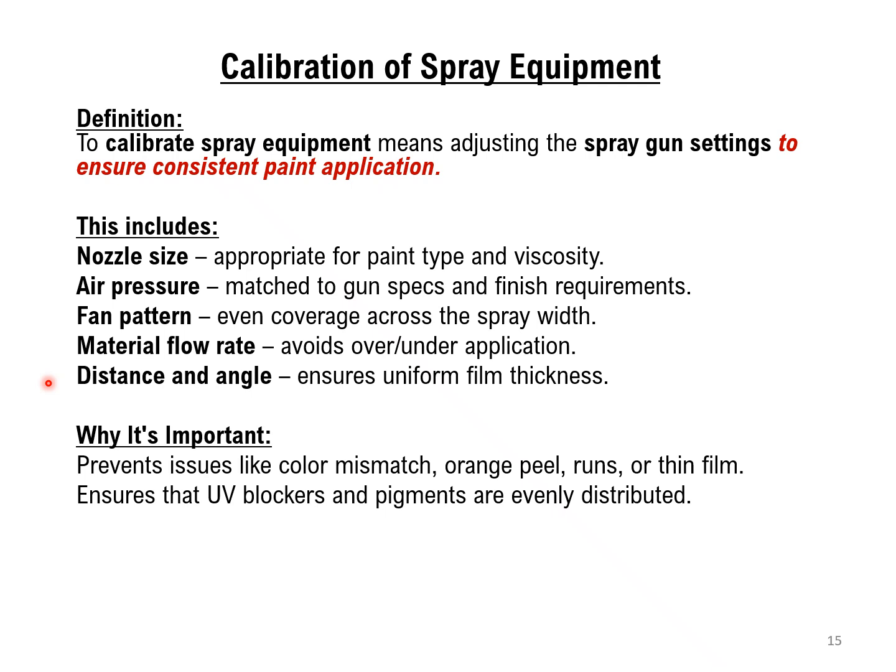It is important to prevent issues like color mismatch, orange peel, runs, or thin film. It ensures that UV blockers and pigments are evenly distributed.